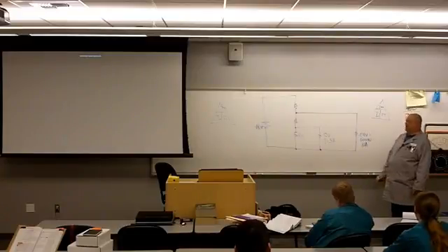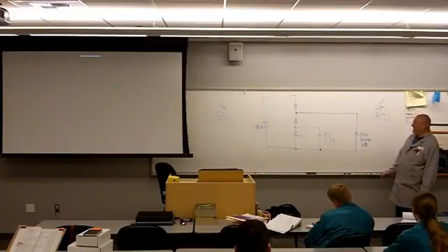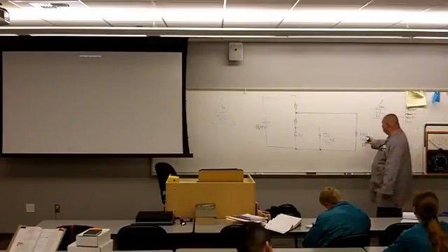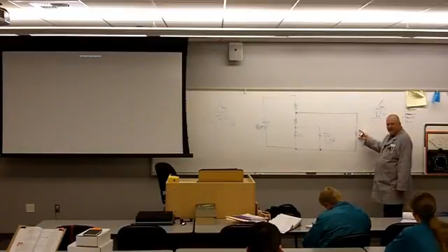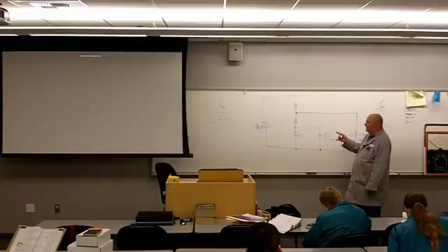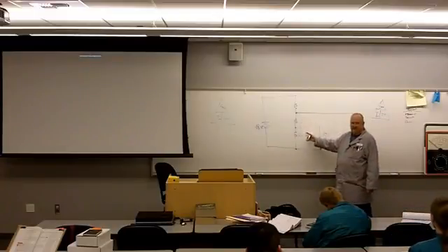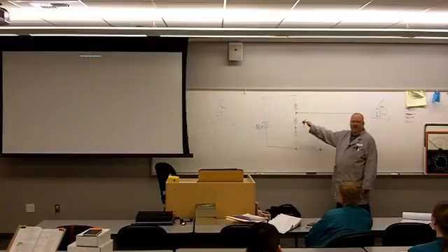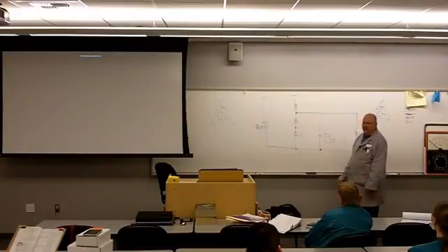Okay. So now what I have is a circuit, a viable circuit. And by the way, if I want 24 volts here, and I am getting this voltage across these two resistors, what voltage must I be dropping across this resistor right here? How much? 12.